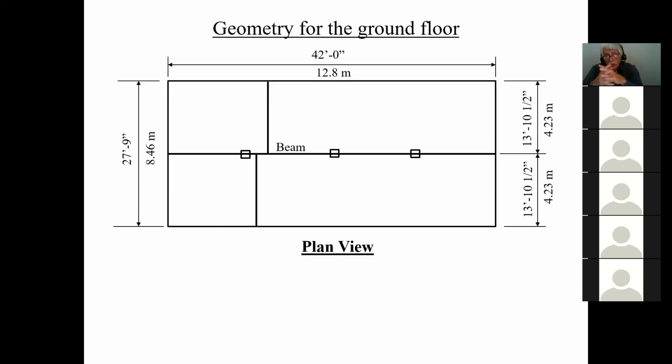That's very common when you go into a residential house: you'll see that most of the beams are made out of steel, sitting on steel columns, and the floor is made out of wood. So don't be surprised if you have a hybrid of both. The reason why I don't like to mix and match is because wood tends to shrink, steel doesn't, and depending on how it's built, the shrinkage of the wood can start being restricted by the steel. Then you can start getting cracks and so on.